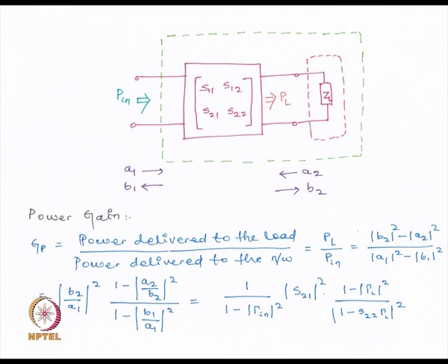Now, in microwave engineering, we shall of course be studying this in more detail. This term power gain, or operating power gain, comes across frequently. Now, what is this power gain? Suppose we have a 2-port network with a load connected, then the total power that is actually delivered to the load. By actually delivered, we mean it should not include that component which is reflected from this interface, over the power delivered to the network.